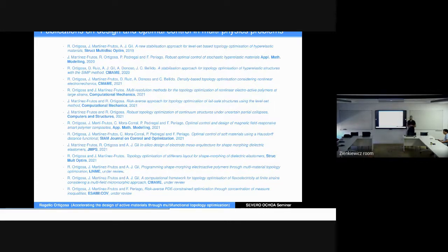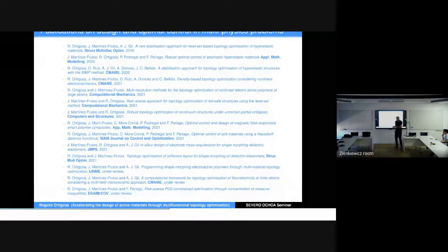Now, when you do this optimization and you have these nonlinear structures, what happens if you have a mechanical instability during the process of shape morphing? Do they appear, and if so, how do you address that? Before jumping into the multiphysics context, we jumped into just mechanics, and we tested very large deformations. I didn't have experience in topology optimization, and I thought it was going to be something straightforward, something easy with SIMP and level set. We tested that, but you have plenty of instabilities, especially in the case of SIMP, instabilities associated with intermediate densities, and you don't know what's going to happen.